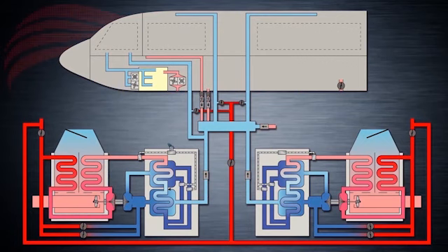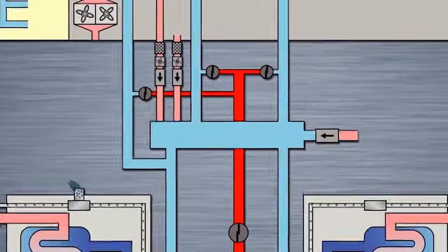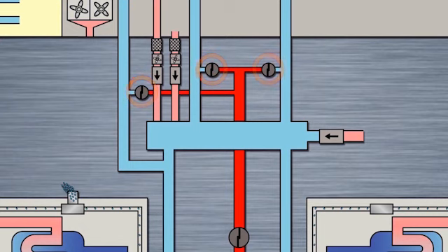Trim air is extracted from the bleed air that passes through the flow control valve we mentioned earlier, and is ducted towards 3 trim air valves, one in each cabin zone. In simple terms, the packs deliver one air temperature according to the coldest cabin zone. Trim air heats up the other 2 cabin zones to increase their temperature to the desired automatic temperature of 24 degrees Celsius.